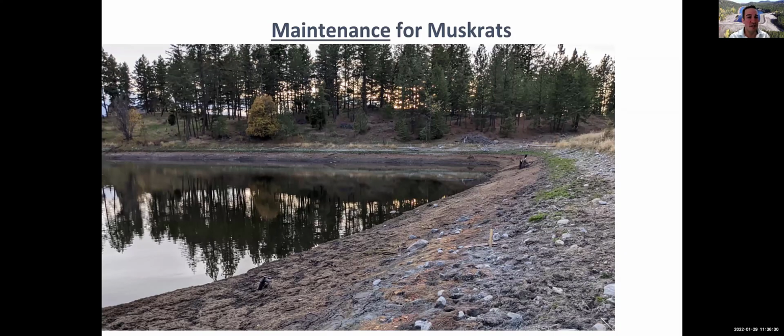A lot of this stuff, again, is, we've got trees that are a problem, some short seepage paths, you've got rotted out roots and things, but you still have the same kind of approaches, right? A lot of this stuff you can do as just maintenance. You can fill in a little hole. I think as a rule of thumb, as long as you're not excavating with equipment, you're not really doing work on the dam. But anyways, you can always contact your DSO.